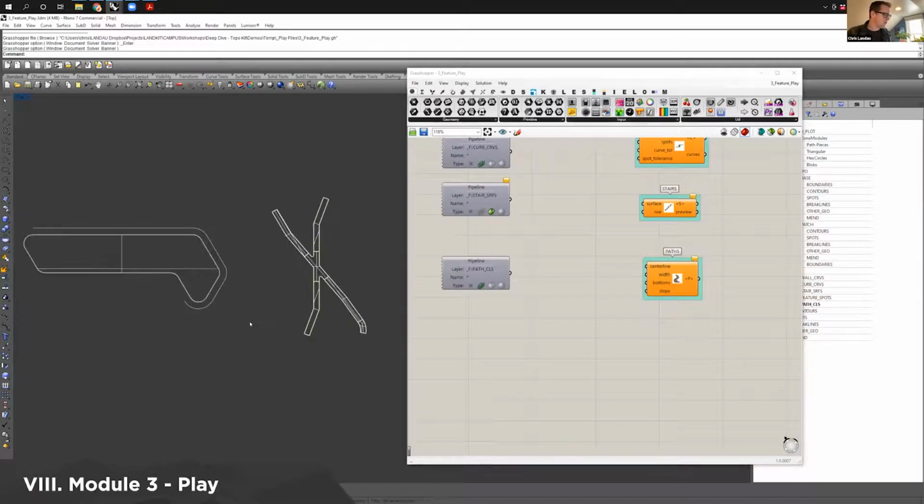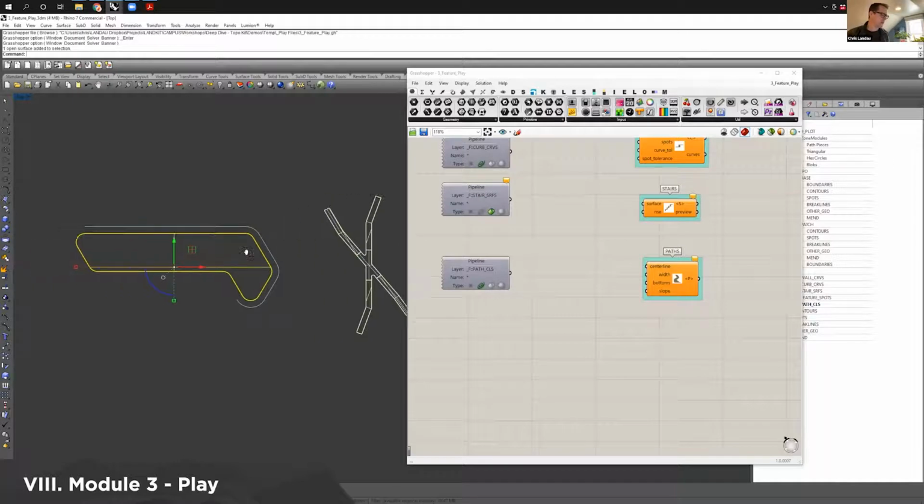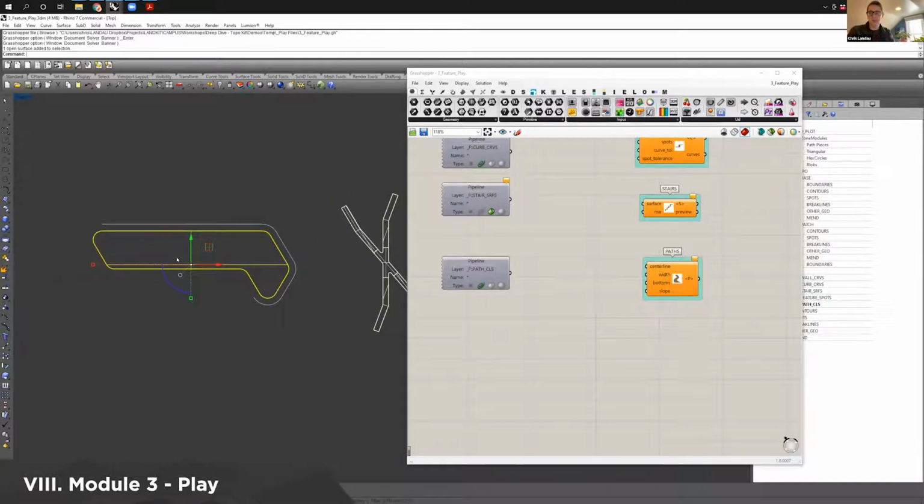One of the things I mentioned earlier is that these areas are great for a few reasons. One is that you can trim them, join them, merge them. You can untrim a shape, so if it has a hole in it, you can untrim that hole. They're very flexible, and they have a lot of memory in them. One of the things they remember is the actual curves that they're being split with. And as long as everything's flat, those curves are essentially the line work that you use to split it with. And that's sort of the approach.